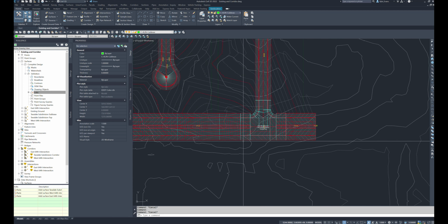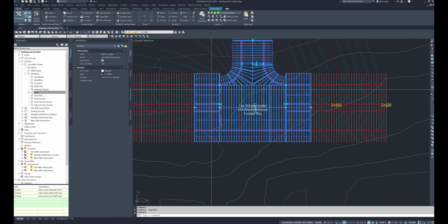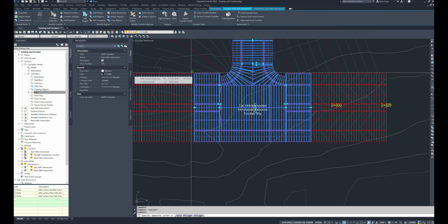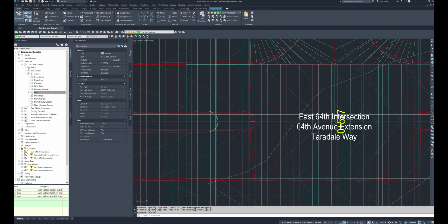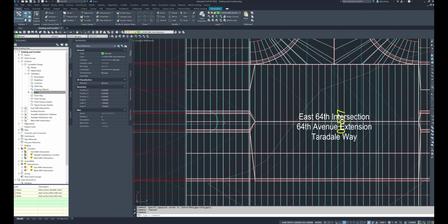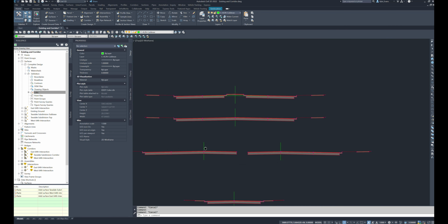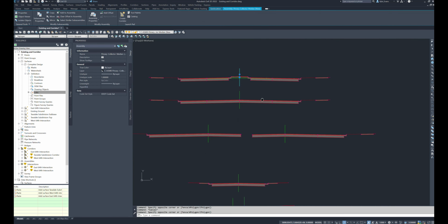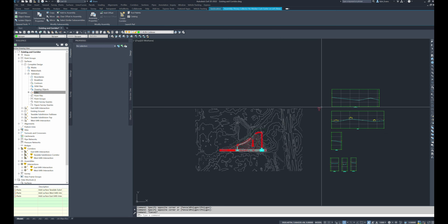All right, the next thing we're going to do is Civil 3D builds these intersections essentially in 3 pieces. So we're going to modify this one. I'm not going to bother modifying the left one. The steps will be the exact same. But we have our primary collector with the median, primary collector with no median, and primary collector with median. Where I have these bull noses is essentially where the median needs to stop. So we need to go in and modify our intersection assemblies. And that is why we made the median one, the non-median full-size one, and then the intersection specific ones.